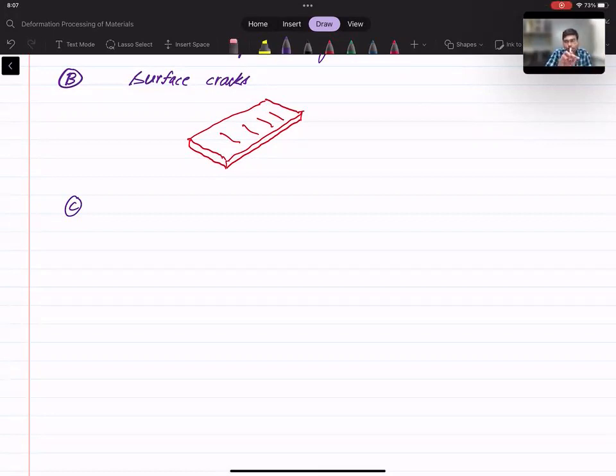Say from the center line, h1 is the distance of the roller at the bottom, and h2 is the distance between the center line and the top roller. And if these separations become different, then in that case the material sort of gets split from the center line and an alligatoring defect is observed.